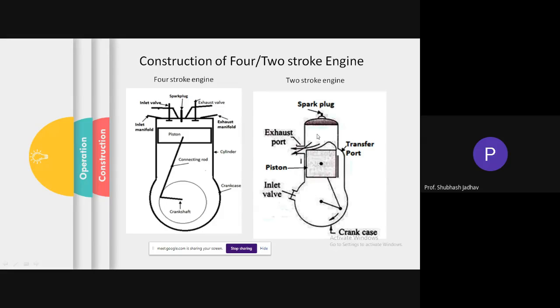Now the piston will move up, reach the top dead center, and when it is coming down, what is happening? When it is coming down, the mixture over here is going to be compressed. Correct? The pressure will go on increasing. Some stage will come when the pressure outside and inside will become equal. Once the pressure becomes equal, thereafter any movement of the piston in the downward direction will result in the pressure here becoming positive, more than atmospheric.